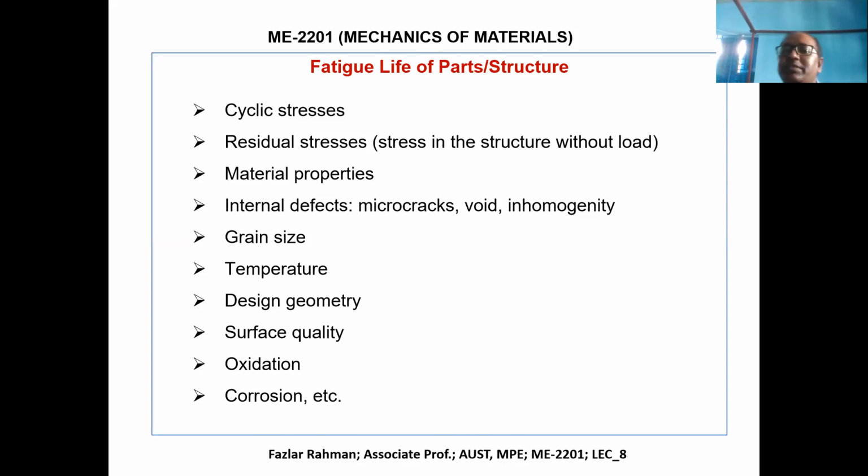Why? Because of the weather, the temperature, the humidity, the stiffness of the rubber is gone. So even a part you keep on the shelf without using has a certain life. This is called shelf life. Some companies say a shelf life of 3 months, and they'll say reject it, even if it is good. So fatigue life, there are some factors that affect the fatigue life.